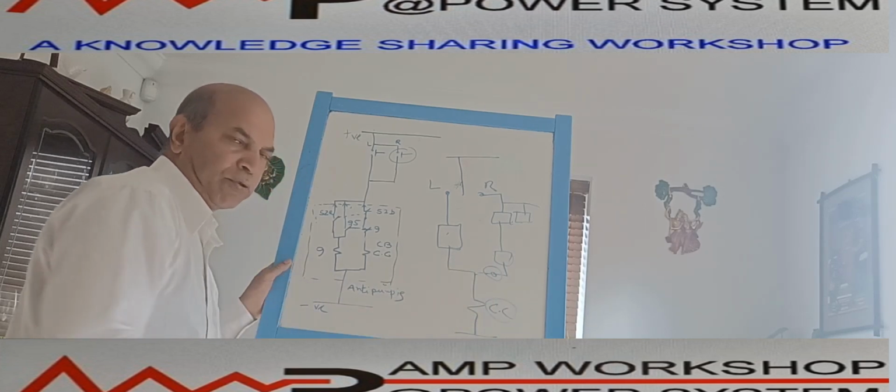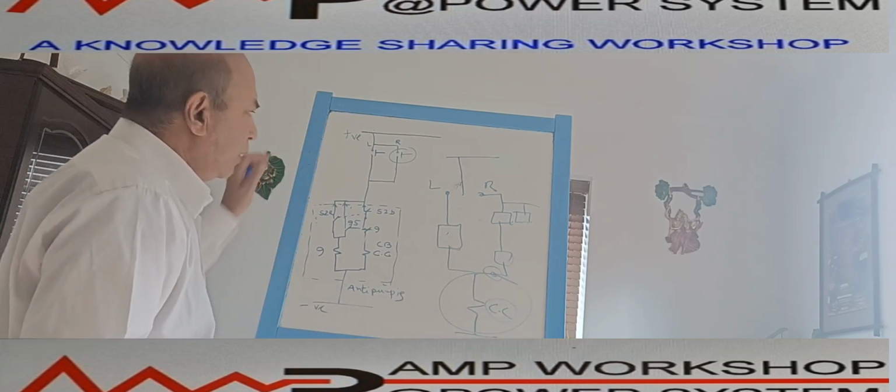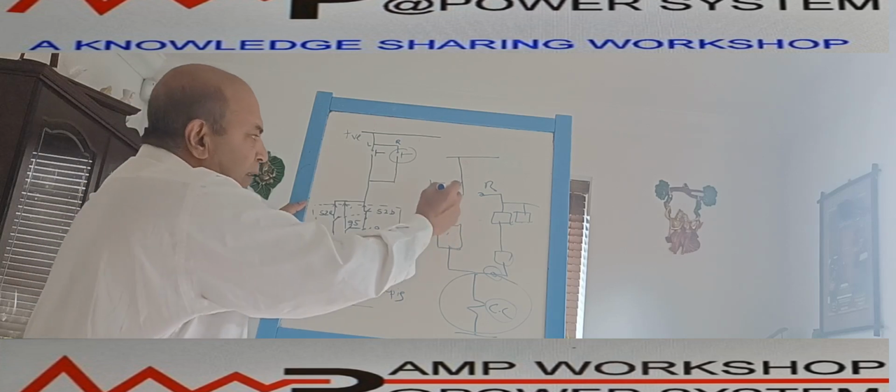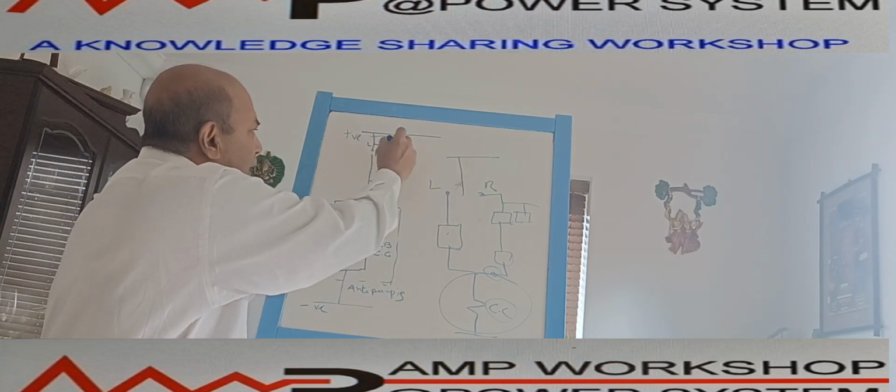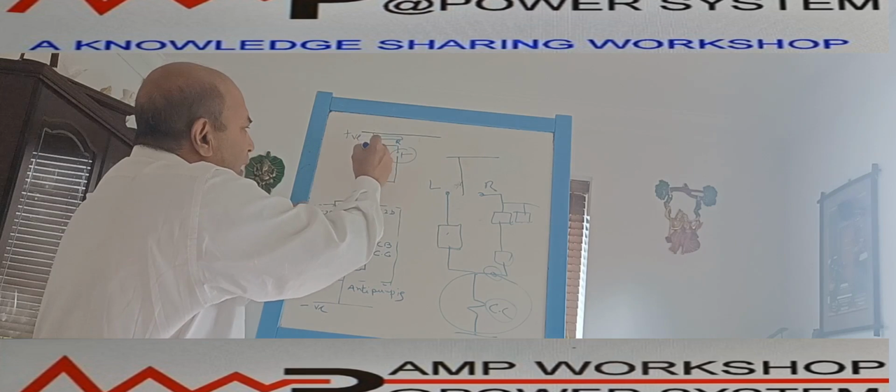Similarly, from the remote position, we have various, multiple remote commands over here. Then from the command, there is a disconnector interlock, and then it goes to the closing coil. A permissive command is also here. Then it goes to the breaker closing coil. This way we have shown this. So this part we are now showing in detail. For simplification, I have shown the local remote selector in this location, so you can select either local or remote.